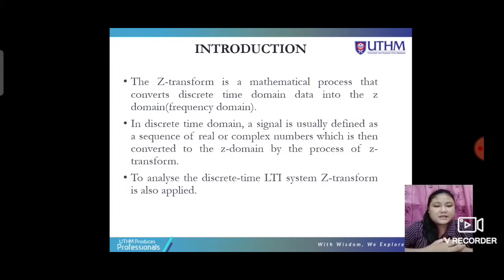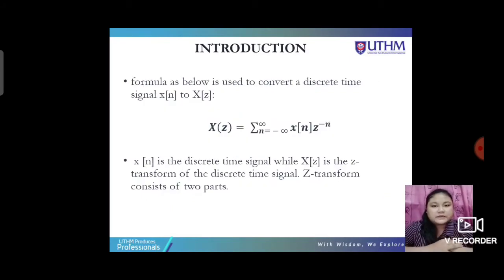So for the sake of analyzing the continuous time linear time invariant (LTI) system in this project, the Laplace transform is utilized. To analyze the discrete time LTI system, the Z transform is also applied. In this assignment, we apply the formula below to convert the discrete time signal x[n] to X(z).